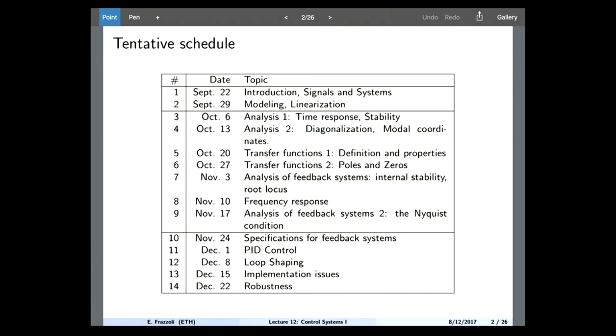Remember that on the Bode plot, the way you represent the specification is a bunch of obstacles on the left. Those are the specifications about command tracking and disturbance rejection. You have obstacles on the right that correspond to noise rejection. Then what you want to do is take your loop transfer function and literally bend it and steer it in such a way that avoids all those obstacles.